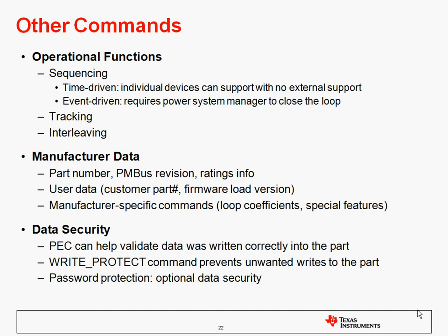If you want an event-driven sequencing algorithm that requires the prior device to have come up successfully before enabling the next device, there is some interaction with a system manager in order to close the loop. Tracking and interleaving are also features that are available in certain devices.